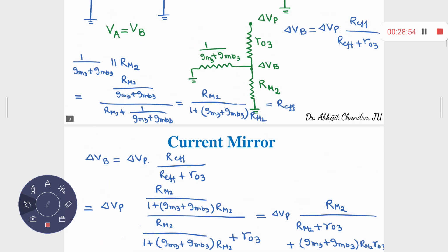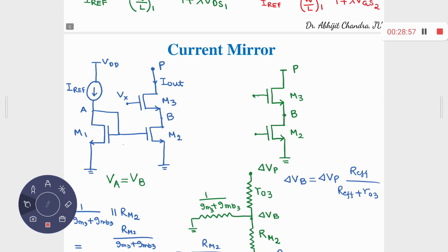We have got this circuit. And now you have to find out what should be that voltage. So this circuit is good enough for providing you current mirroring effect, a copying circuit, and now you have to find out what should be that particular potential. Remember that this M1 is already in saturation. You should not be bothered about M1 because gate and drain are shorted. But you have to ensure that M2 and M3 must be in saturation.